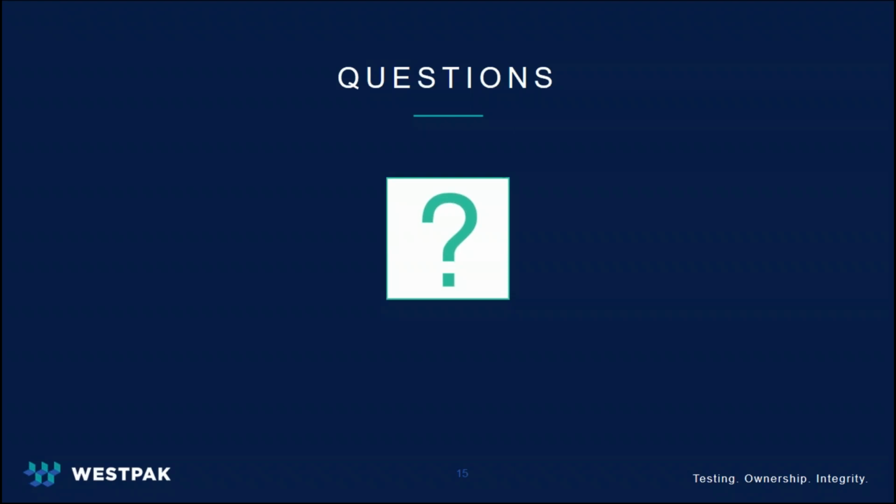Okay, Greg, a question just coming in here about dye testing, another one on dye testing. How reliable is dye test, and how often is this performed for medical device packaging? Dye testing is very reliable. It is used to check your seals to make sure they're intact. Again, it's hard to determine the surfaces with dye testing because you have to let it soak in the dye material. We see probably 2 or 3% of our customers use dye testing to do seal validation.